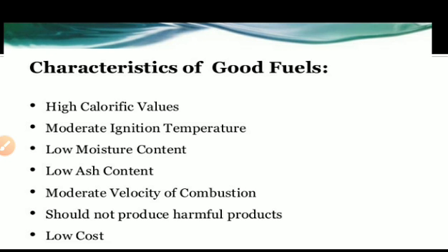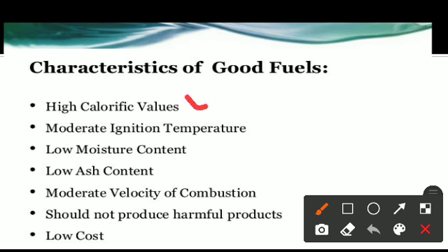Next, let us learn the properties of a good fuel. It has a number of properties. Let us learn first, high calorific value. The calorific value of a fuel is the amount of heat produced by the complete combustion of a unit weight or volume of a fuel. A fuel with high calorific value is more useful. Fuel with high calorific value is called a very useful fuel.